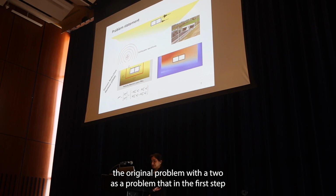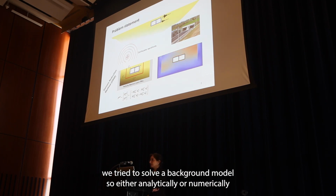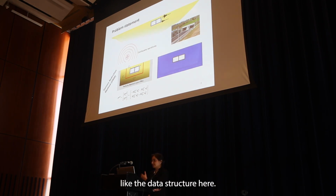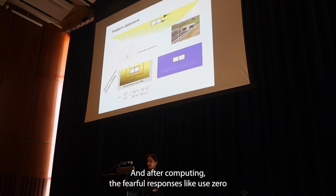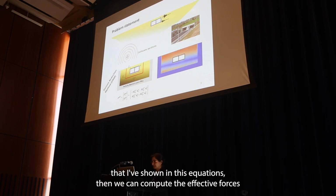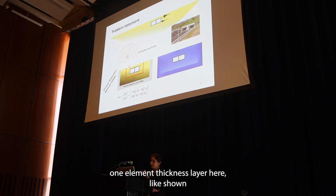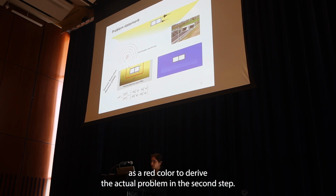In the first step, we try to solve a background model, either analytically or numerically, computing free field responses where we don't have the localized heterogeneity like the buried structure here. After computing the free field responses like U0, shown in these equations, we can compute the effective forces, defined on a one-element-thickness layer, shown in red, to drive the actual problem in the second step.